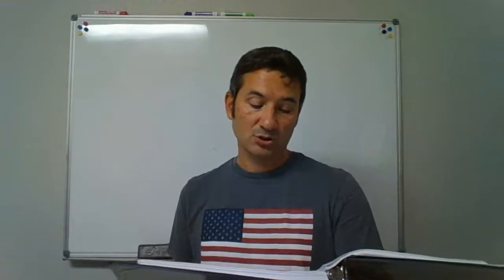Pressure marking of storage tanks. I'll let you read that. The temperature controls. Once again, hot water supply systems should be equipped with automatic temperature controls capable of adjustments from the lowest to the highest acceptable temperature settings for the intended temperature operating range. In a water heating system where temperatures exceed 140 degrees, a means such as an approved mixing valve shall be installed to temper the water for domestic use. So it says the hottest water coming out of there for domestic use ought to be 140 degrees. And if you've got a heat source that is heating it up above 140 degrees, you ought to have some means of being able to cool that down.